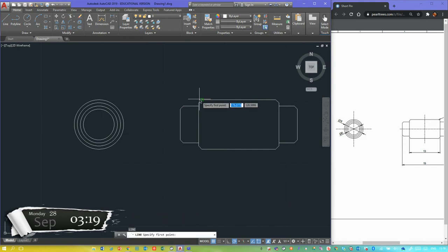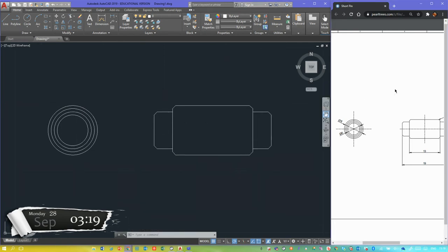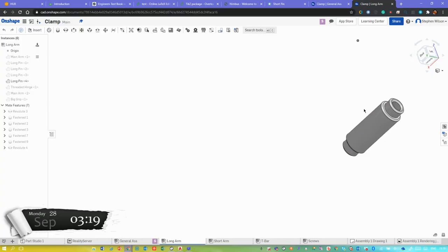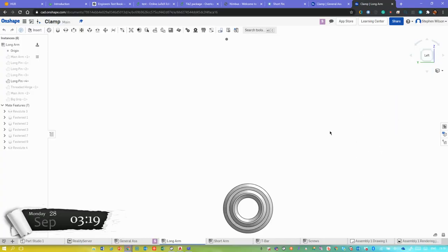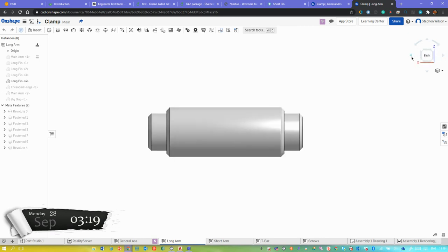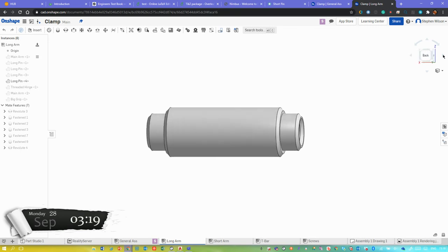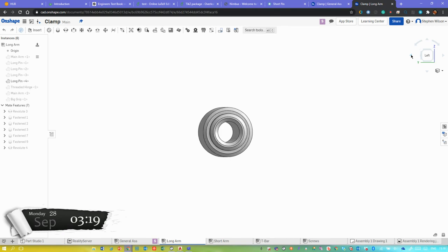And you can see, if I go from there to there, it's at the same point. If I go from that corner to there, we see that the circle touches at the same point. So we've got that relationship between our two views. It's the same object. All we're doing, quite literally, is just turning it from one view. Let's move that up a bit, like that. So we shouldn't have things changing sizes as we move from one view to another.